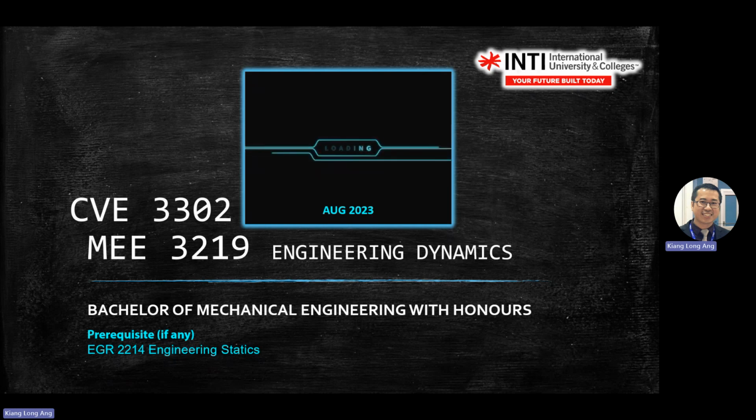In chapter 2, you deal with four kinds of force: external force, weight, friction force, and normal force. Then the motion depends; you only have two, linear or curvilinear motion. So this is basically what chapter 2 is about. The difficult part is that some of you might miss the normal force because you forget that a contact surface has a normal force, right?